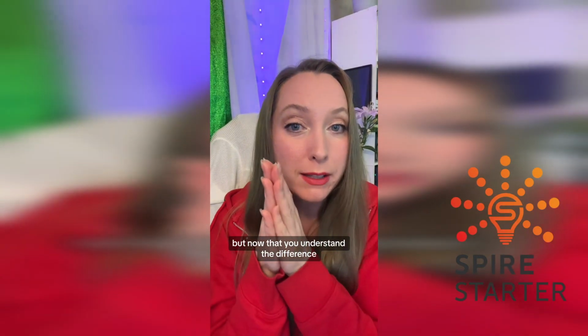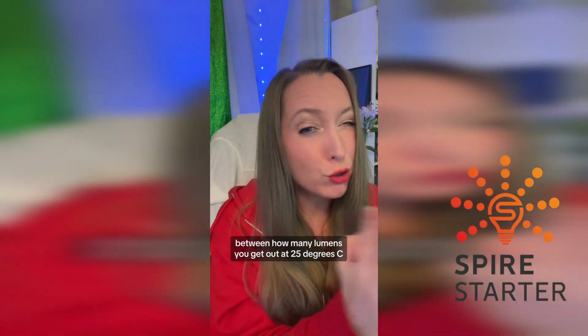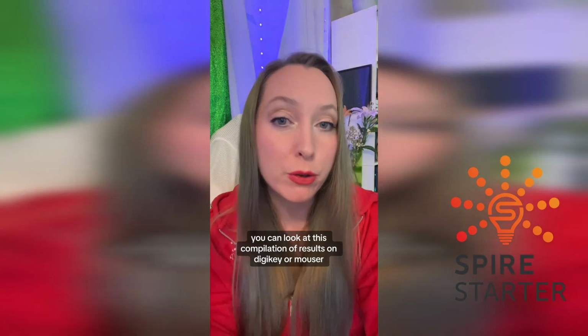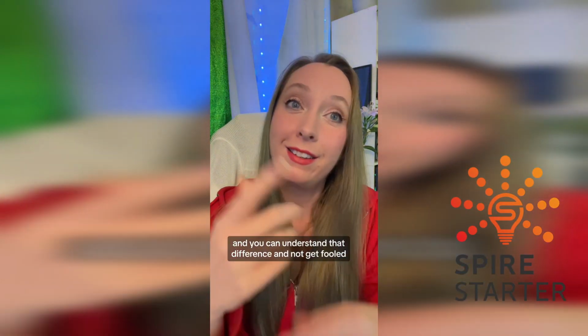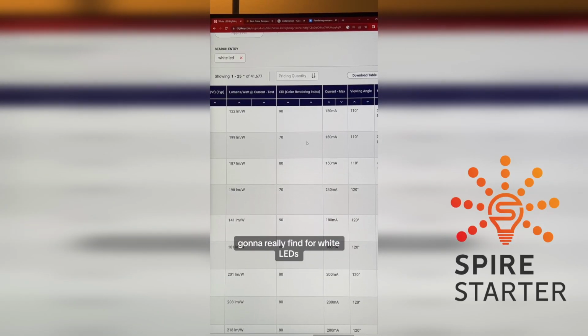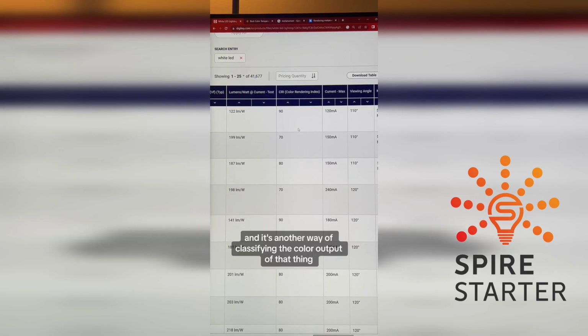But now that you understand the difference between how many lumens you get out at 25 degrees C versus 85 degrees C, you can look at this compilation of results on DigiKey or Mouser, and you can understand that difference and not get fooled. Moving on to CRI, Color Rendering Index. This is another one that you're only going to really find for white LEDs, and it's another way of classifying the color output of that thing.